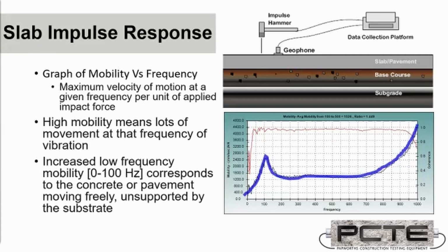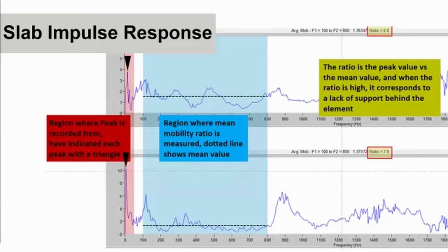the frequency of those energies again, and we're looking for a comparison between the low frequencies up to about 50 to 100 hertz and comparing those to the average frequency. Practically, we use this to determine if a slab or wall or other element, like maybe a pipe, is properly supported by the ground or earth behind it.